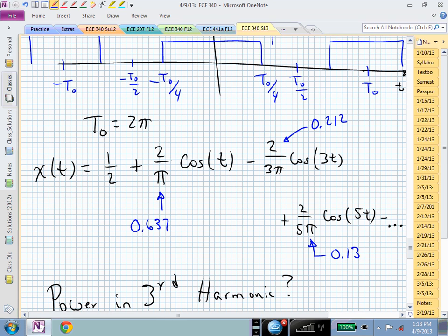Where the cosine of pi is just minus 1. And that would account for that negative sign. In terms of what's happening, that's just a decrease in the average value of x of t in the time domain, that DC value. The angle at DC, in this example, 0.